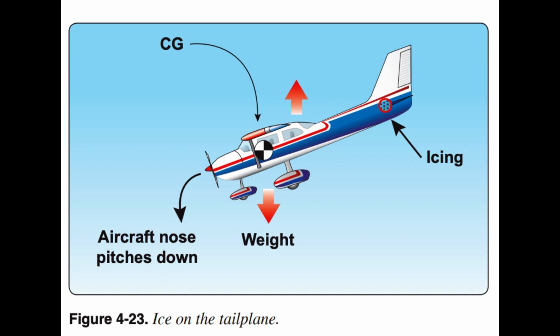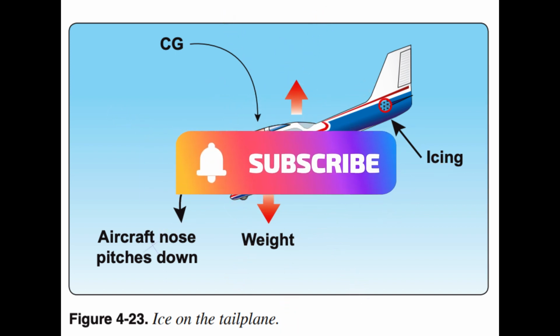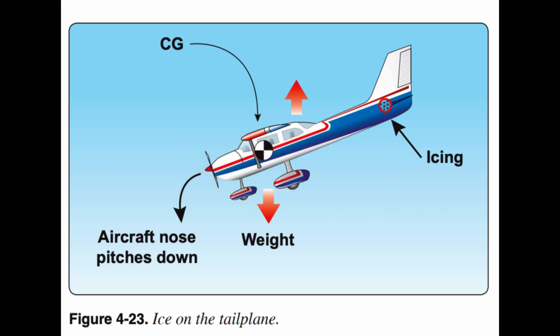Antenna icing. Because of their small size and shape, antennas that do not lay flush with the aircraft's skin tend to accumulate ice rapidly. Furthermore, they often are devoid of internal anti-icing or de-icing capability for protection. During flight in icing conditions, ice accumulations on an antenna may cause it to begin to vibrate or cause radio signals to become distorted, and it may cause damage to the antenna. If a frozen antenna breaks off, it can damage other areas of the aircraft in addition to causing a communication or navigation system failure.